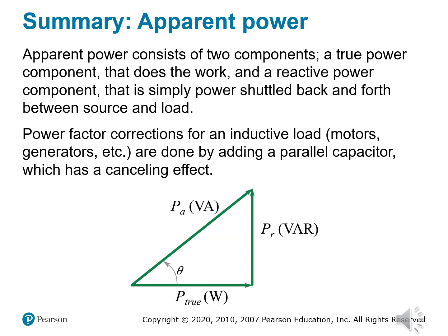Power: the triangle that powers a grid. So we've looked at real power, reactive power, and the role of phase angle. Let's bring all those things into a single unified visual: the power triangle. At the top of the triangle, apparent power, the power your utility meter sees, but not all of it goes to doing work. So here's how we break this down.